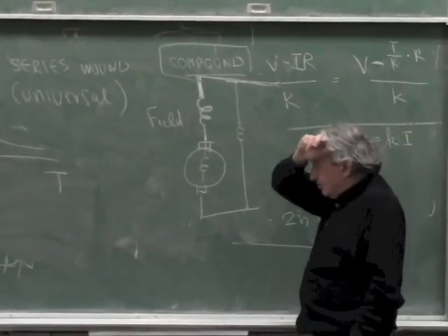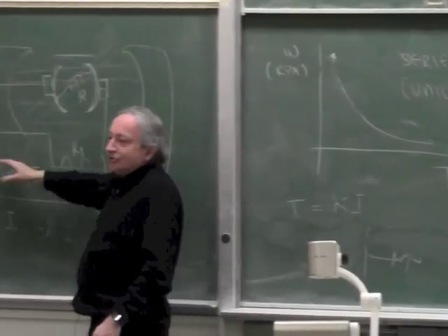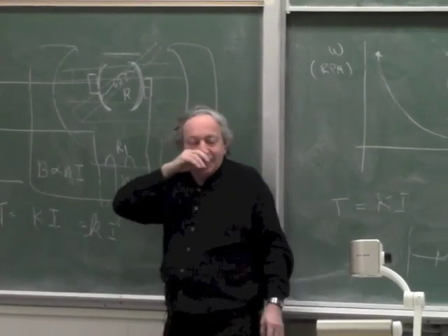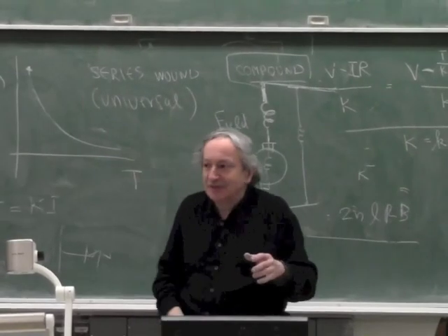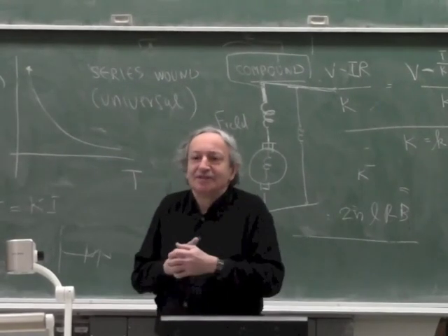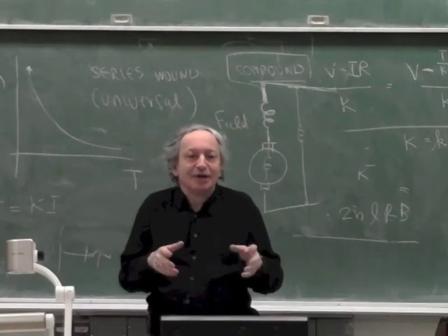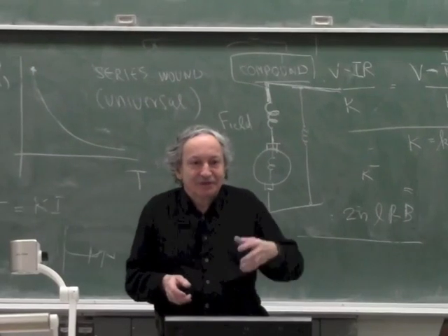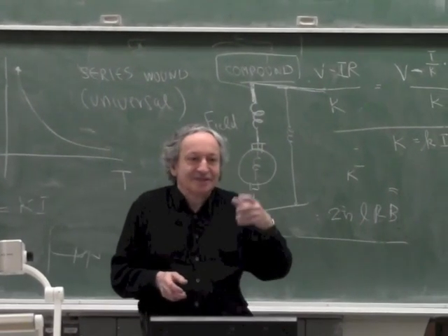The moment there is a minimum current because of friction, the B cannot drop because the I doesn't drop, and then it stabilizes. But if I took a bigger motor where the friction is not significant, it will keep running faster and faster. And I think the best example is if you take your power saw router at home, and if you don't load it, it'll make a very, very high-pitched noise, which you can roughly guess the RPM from that.